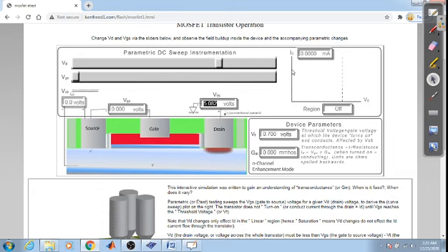Now let us give a sufficient amount of voltage. Just look over here. Still it is 0.6 volts. At 0.8 volts, just look over here, the current is flowing. So this is indicated over here. When you apply more voltage between gate and source, just look over here, 1 volt, more current is flowing. So this is indicated over here.